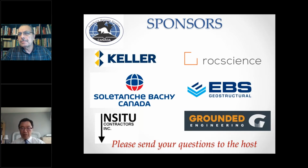Just according to your probably first or second presentation slide, you showed some seepage passing through the shoring piles, shoring wall. Yes, and you mentioned that dewatering, of course, is important for the remedial work. You mentioned that additional dewatering may be considered, of course, but the question for the timing consideration, do you also consider other emergent treatment, for example, grouting or whatever, just because of the timing, to stop or reduce this amount of the seepage? Well, it depends.